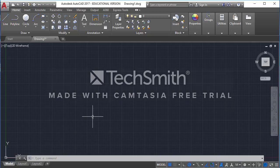As you type things onto your screen, you will notice that they automatically appear on this little bar at the very bottom. Often when you are typing commands, for example, if I type in L, enter, this little bar will tell you what the next step is. So when I typed in line, it said specify first point. From there on my screen, I would specify what my first point of my line is.